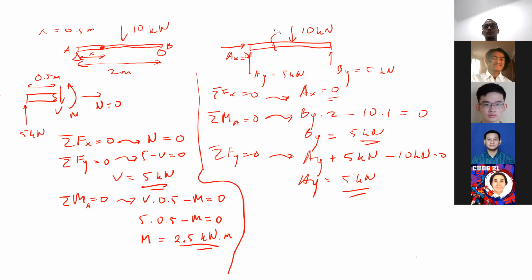Okay, where are we supposed to start, Lilo? We can like the three force, V, M, moment, and normal force. Okay, but before that, we have to draw the free body diagram, right? Oh yeah. Yeah, the section free body diagram. Don't forget about it. After you finish for the external forces, then the next thing that you're supposed to do is to draw the section free body diagram. Then after that, you can solve the internal force and moment using the equilibrium.